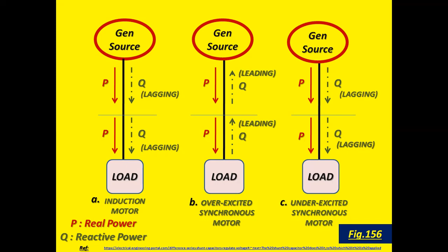Overexcited synchronous motor, leading power factor to the source. Underexcited synchronous motor, lagging power factor from the source to load.